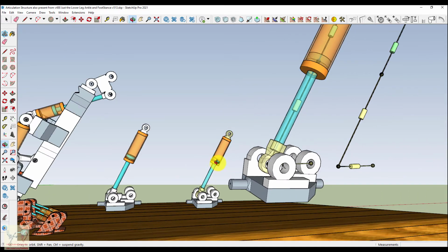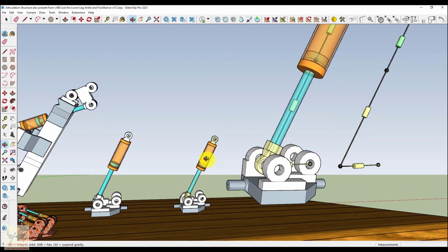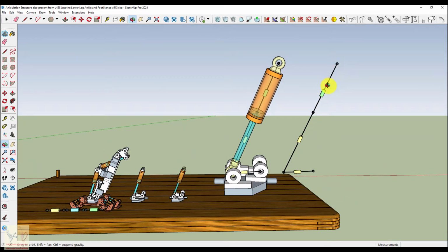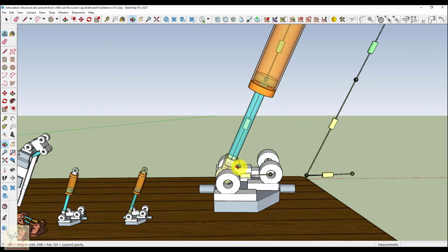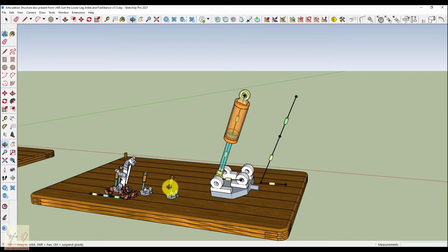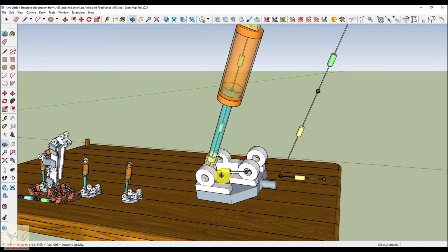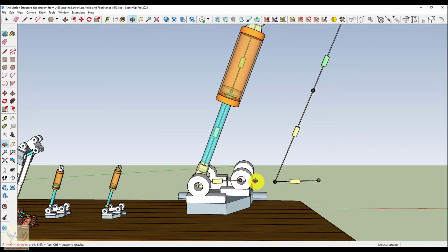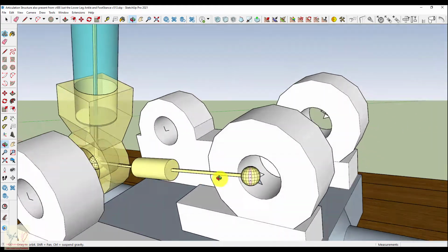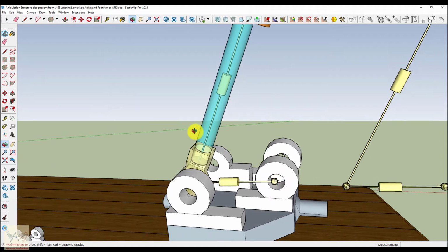And the reason I made this opacity down is so I can show you the articulation features that would be placed inside of it. And the other thing I did with this is I just grabbed it with the scale feature and made it bigger. And I only made it bigger so you can see. And so these now, if you add these little articulation devices in there, these become articulated joints.